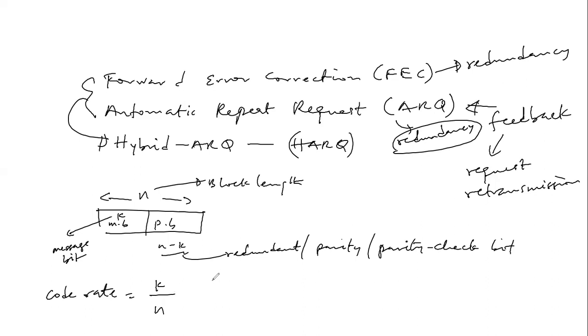And then we have the channel data rate, which is the output rate, which is the same as n over k times Rs, where this is the encoder input rate, while this is the output. Then we also have the code efficiency, and the code efficiency is equivalent to the code rate, because it's the message bits in the block over the transmitted bits of that block.